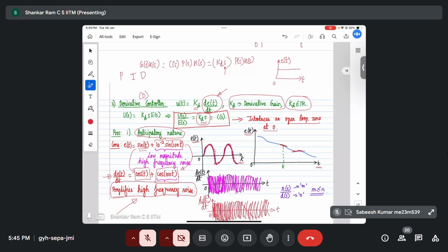However, if you use proportional control, the control input is going to be reasonable, and not at rates which are intractable in practice. So what we do is that we combine proportional and integral, or proportional and derivative, so that there is a balance and trade-off between the nice features of the two blocks, and the controller remains tractable in practice.